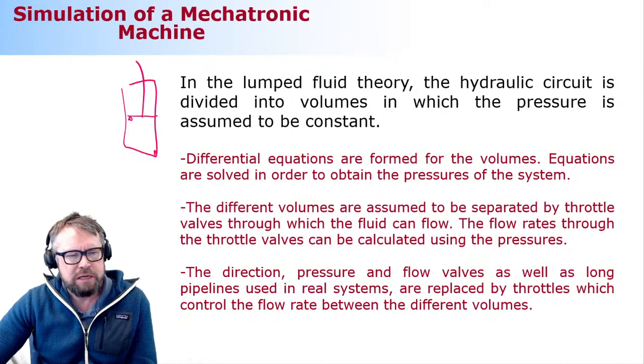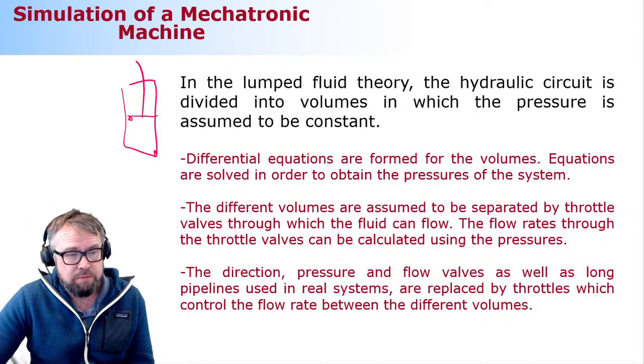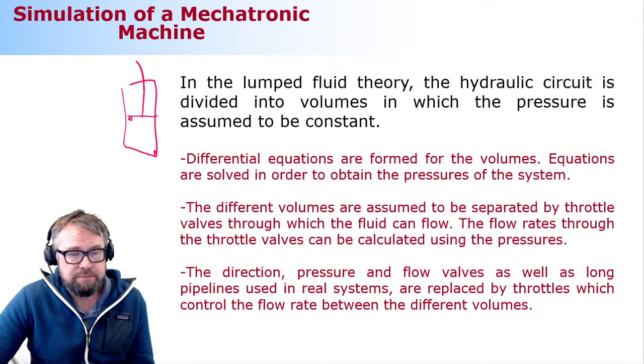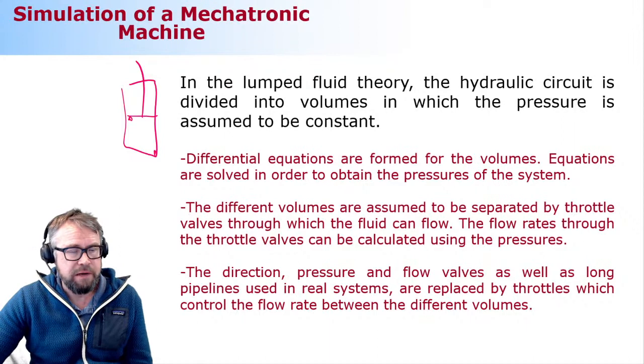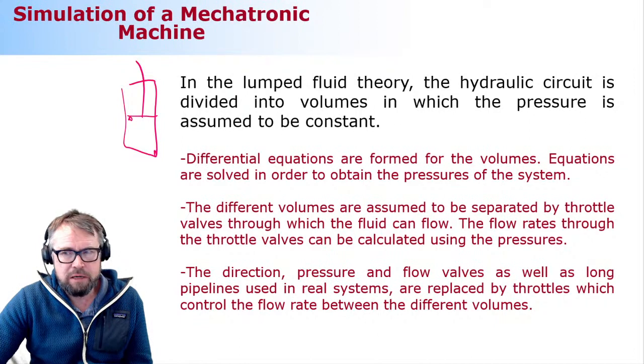Once we do this division, we derive the differential equations, first order differential equations, not too difficult at all, to compute the pressures as a function of time. Then different components, like direction valves and others, if I go back to this first slide, are modeled as simple throttles, which I'm going to show you in examples in a second.